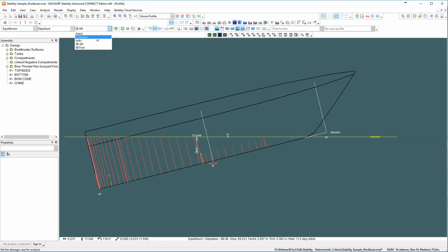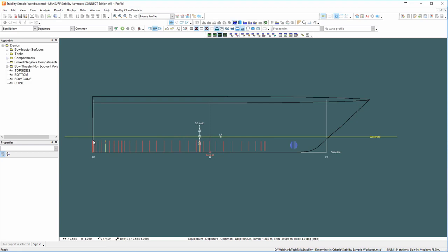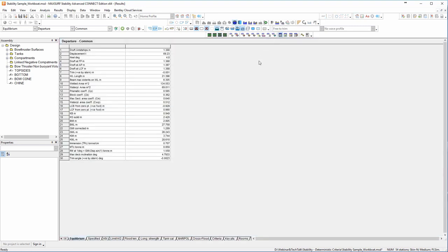So this time, let's go and have a look at when we fill to a common waterline. So we've specified 10%. So 10% flooded isn't particularly far away from that intact case. So now you can see there is one consistent parallel line that covers all of these tanks. If we go back and look in that room definition,